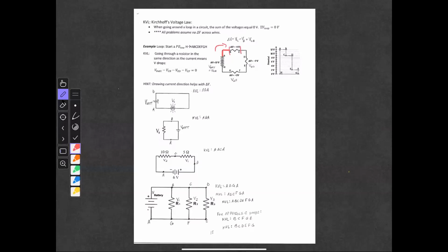So you basically have your maximum voltage coming out of the battery. We could say the voltage from A to H is actually the voltage of the battery. And then when it goes through B to C, or C to B, depending on which probe you put on which side, black or red, you're going to find out that this is a negative voltage.